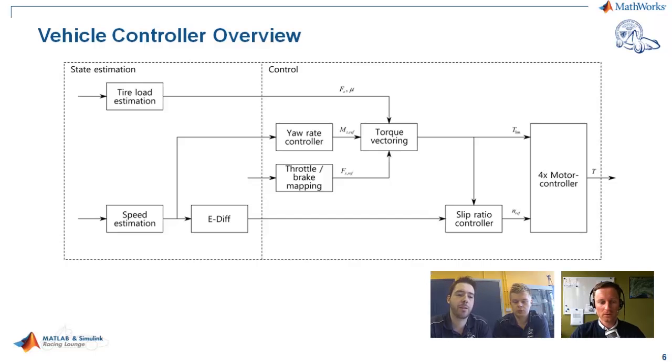Apart from that we also have an optical speed sensor which looks at the road and sees that the car is actually moving. And finally, we also have accelerometers, which we integrate to again estimate the velocity. So we have 3 different methods. At the end, we combine these measurements using a Kalman filter to get one really accurate estimate of the velocity. Okay, got it.